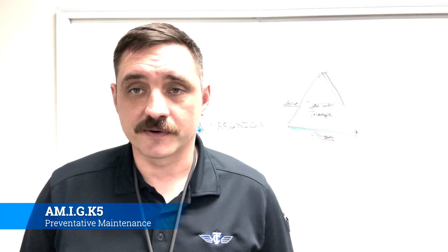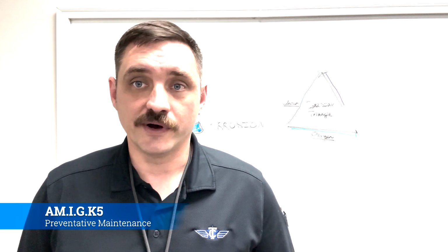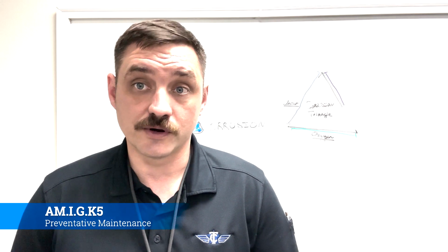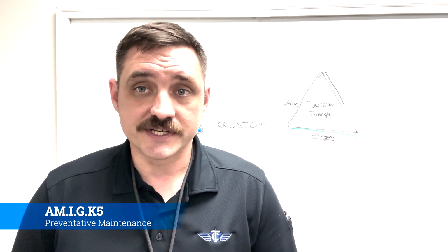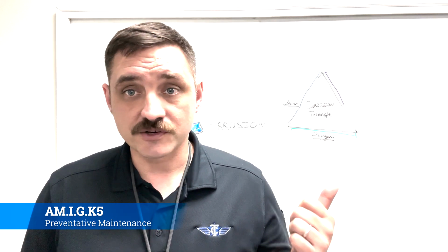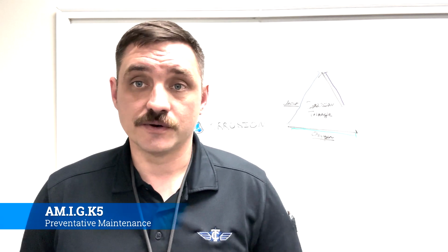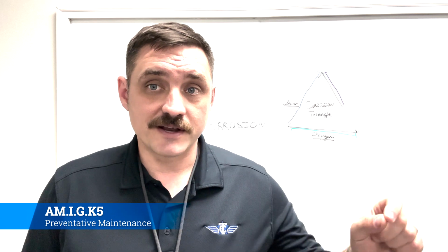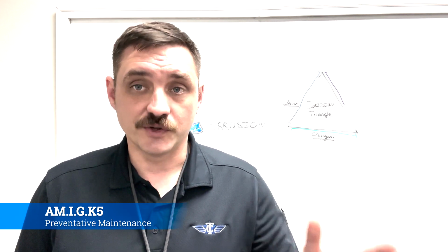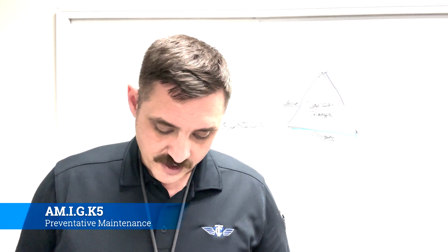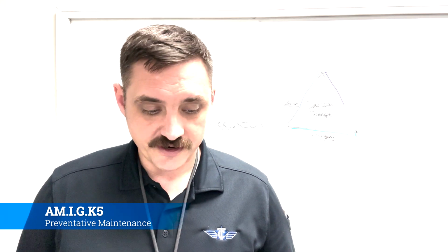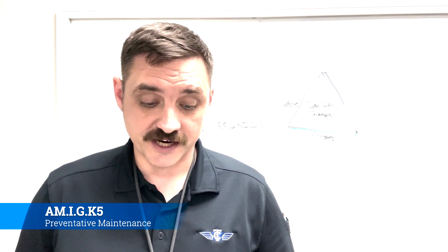Staying on top of the preventative maintenance of the aircraft will help prevent corrosion. A lot of times corrosion is set up because things aren't greased, things aren't lubed, things aren't cleaned. So if you simply just do what the maintenance manual tells you and you stay on top of it, you will prevent corrosion. Detailed inspection for corrosion and failure of protective systems.